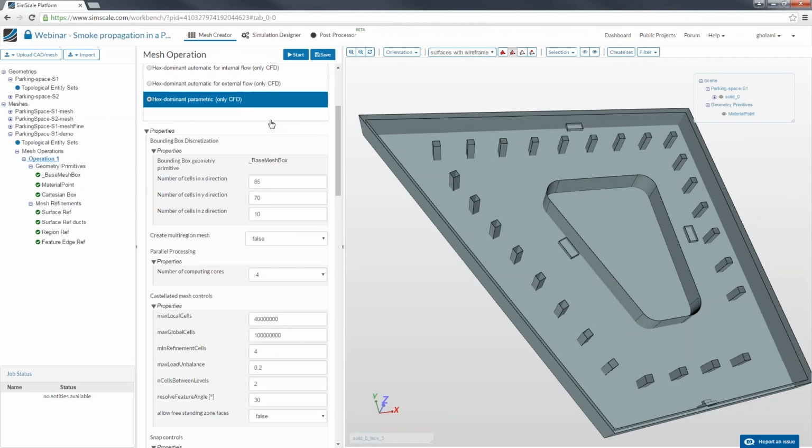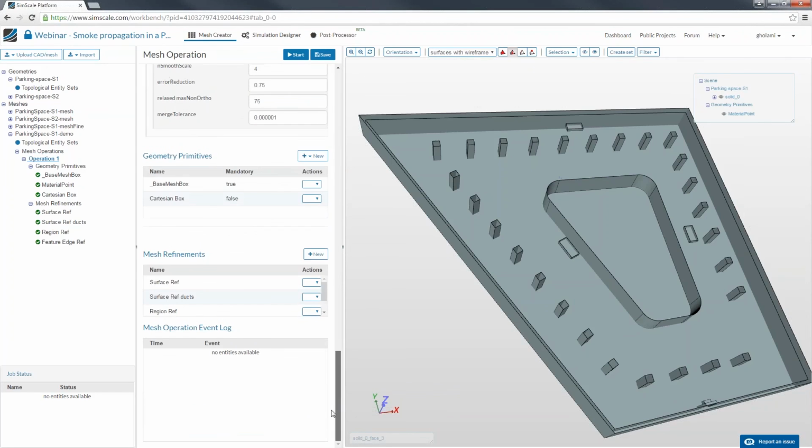Based on your specific application, you could be interested in decreasing or increasing these. But again, we provide values that fit the kind of application you want. So if you have requirements on top of that, go ahead and change these as well. For the projected number of the cells that our mesh is going to have, we decide that 4 cores are enough. So this would be enough for this set of settings.